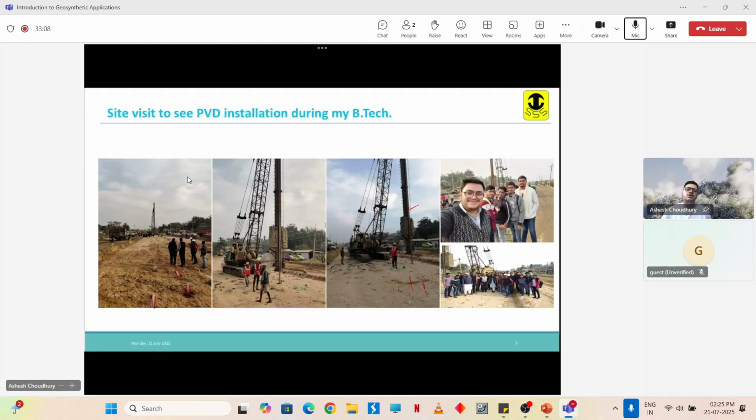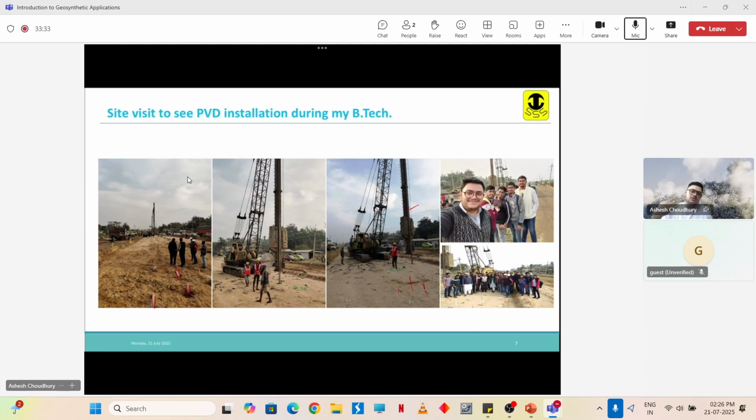Sand drains are difficult to construct, and they are also prone to a lot of damage. So instead of sand drains, we can use PVDs. You should have studied sand drains in your basic soil mechanics courses, when you studied radial consolidation and all this stuff. So these PVDs are an advanced geosynthetic that is used for radial consolidation, for accelerated consolidation.